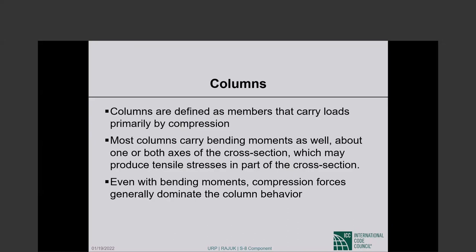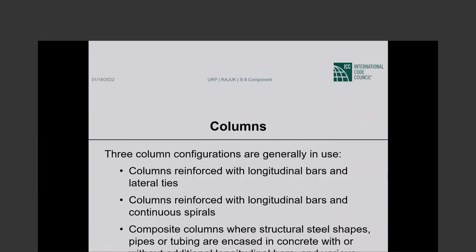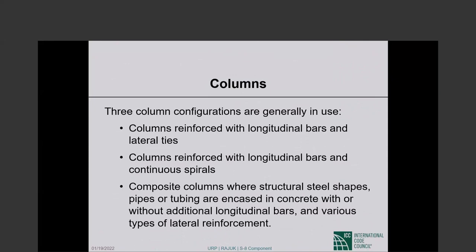Now, even with bending moments, compression forces generally dominate column behavior. That is, again, the key thing that we are talking about, compression-dominated behavior. Basically, all the time, not necessarily all the time. Okay, there are beam-like columns, low axial load, high bending moment. In any case, we have in mind compression-dominated members when we talk about columns.